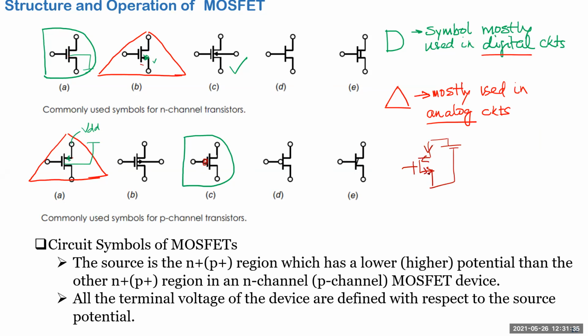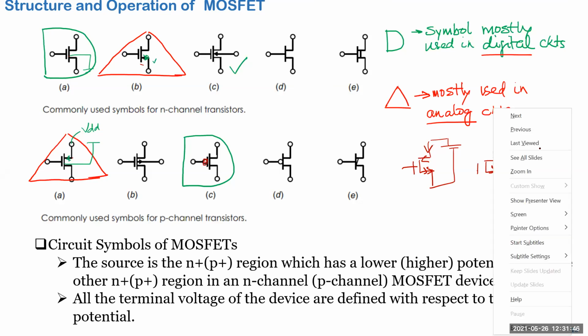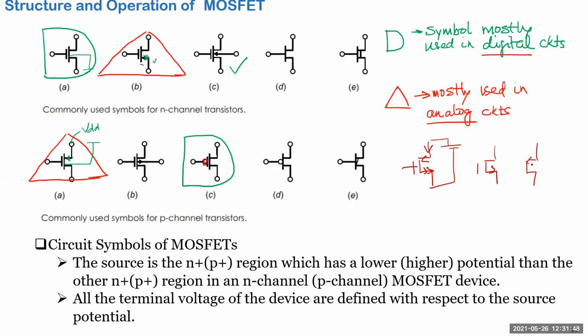So that's the direction. But like I said, you'll get a schematic symbol like this, but that doesn't mean you can't rotate it. You just don't want to rotate it, to avoid confusion. And the PMOS is shown with the arrow inwards, because it's the same thing. Your drain and source are biased like this, where the source end is this, and the current flow will be in this direction. So it's showing the flow of the current basically. These are the two typical symbols. The other ones, don't worry about them.